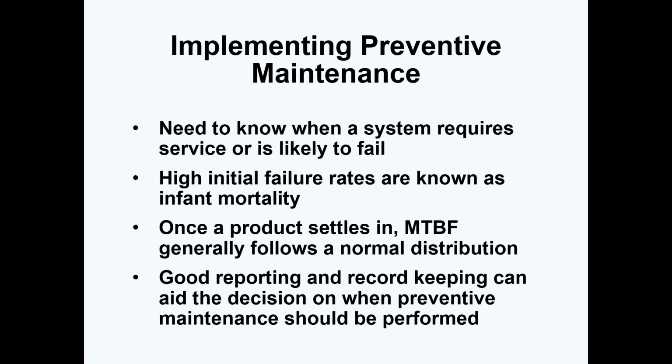Identifying the mean time between failures and documenting possible breakdowns will aid in creating a preventive maintenance schedule to bring reliability back to its normal level and to keep the system functioning as needed. Waiting for the part to fail might affect other components and cause greater damage to the overall system. Corrective maintenance might cause longer downtime and more money to fix.